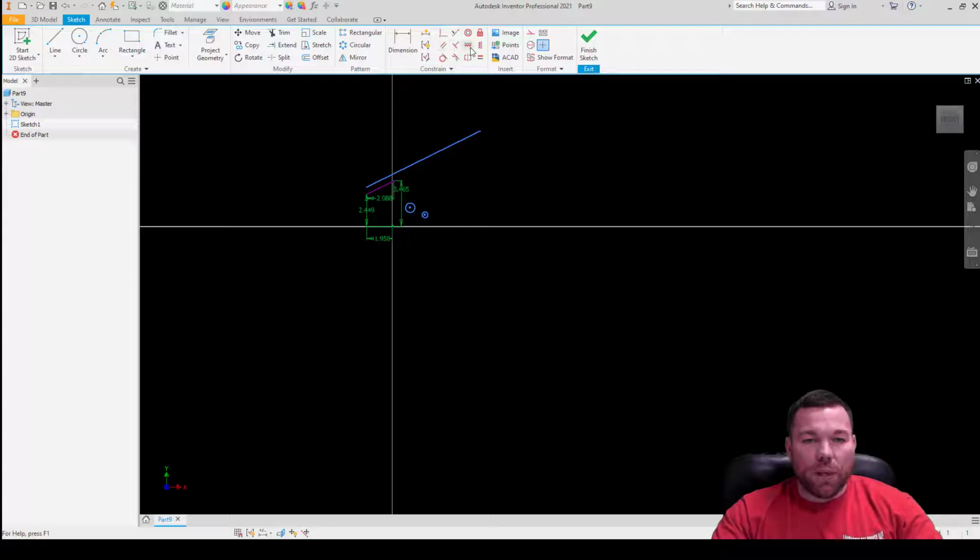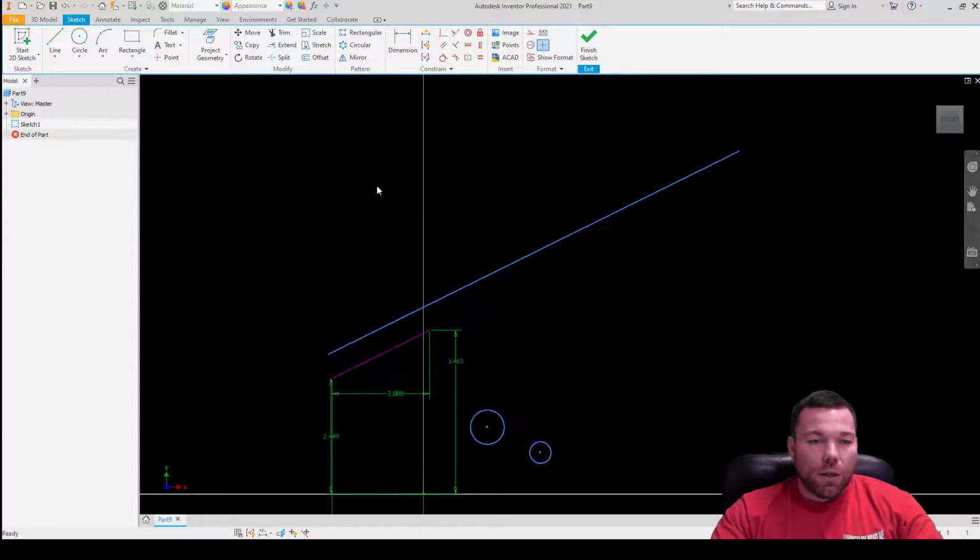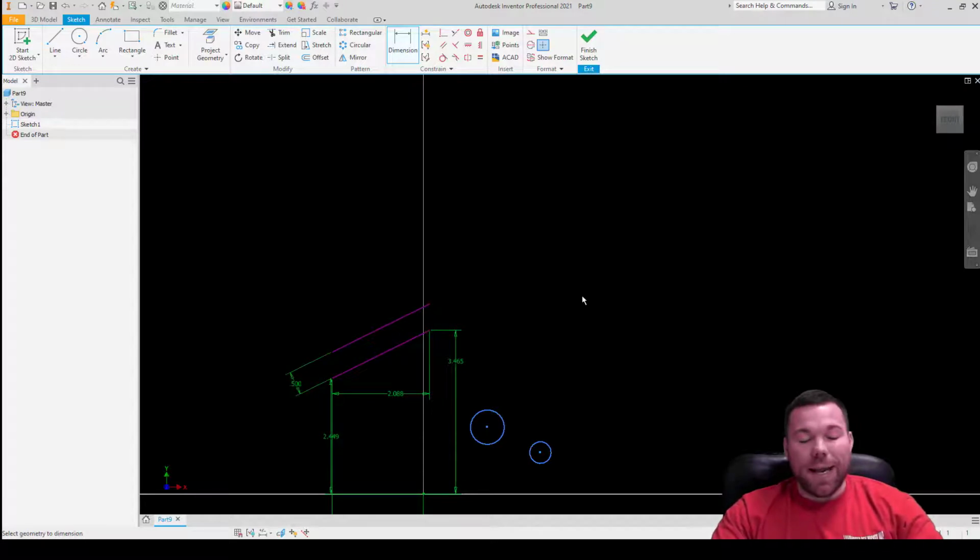We're going to skip over perpendicular. I'm going to go to vertical and horizontal. So I'm going to start with vertical here. What I can do is make that vertical, and I can make this point vertical, and I can dimension this 0.5, and now it's fully defined. What I did was basically just align those points. Since this distance is defined on the lower one, it's got to be defined on the upper one, right? And since I know how far it's offset, it's fully defined.